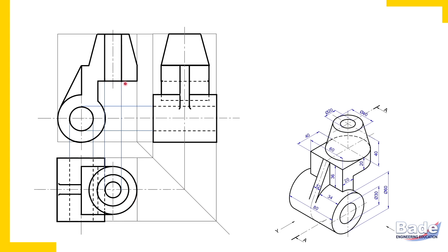So this is that hole. But I have not drawn a dotted line here. Simple. This hole is getting cut by the cutting line. Here is the cutting line. Check here this cutting line. This hole is getting cut by the cutting line. So in the sectional front view, this hole is visible. So don't draw hidden lines here. Okay. Now we'll draw this hole in the side view also. So check those dotted lines. End projectors, you should imagine. And this is how I've drawn that hole. So this hole is in the side view also.